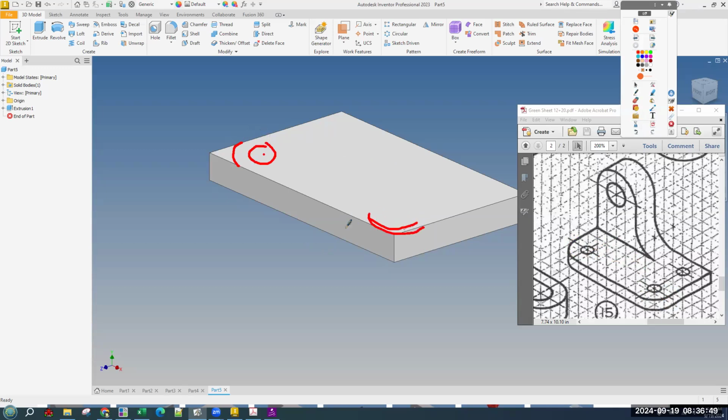When we fillet this off, it'll be rounded. We go to make a sketch, it will give us a snap, the center point. So we won't actually need to dimension the location of these circles. We will just need to give it size. This one still doesn't have anywhere to snap to, so it's still going to be size and location. But the first two will be a freebie.